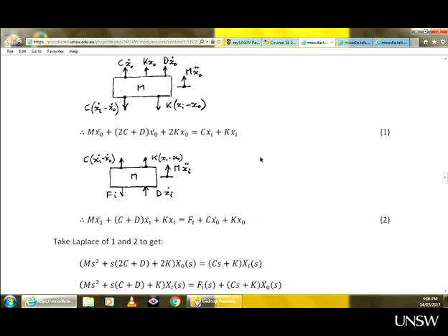Will the transfer function be increased because your input is equal to 1? No, this is the output for given conditions. For this input and these initial conditions, this is the output. But the output is equal to input times the transfer function? No, you can use that only when you have zero initial conditions.